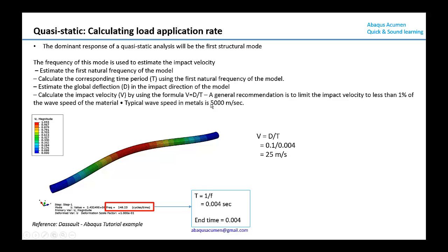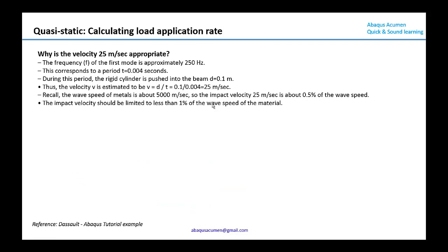So we can go ahead and simulate this analysis using this push velocity of 25 meter per second. In the end, when we do the FE model setup, we will be applying a prescribed displacement to the cylinder with the end time of 0.004 seconds. So those will be the two parameters we take out.